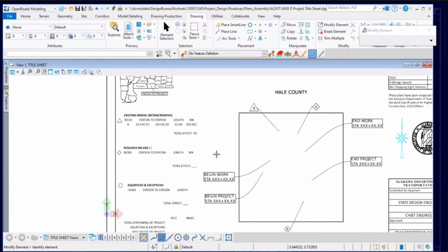If there are no required bridges for this project, move the table and its legend to the left, outside of the sheet boundary. These are tables, so they can be edited by simply selecting the field, and the text editor opens, allowing editing. As before, these tables can be adjusted and additional rows can be added if required. Here, I have populated my existing stations.